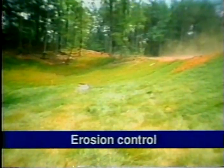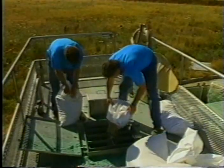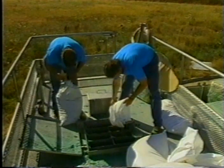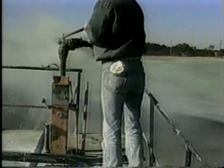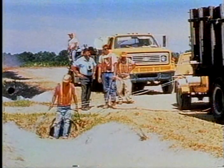Most erosion control methods aim to promote and sustain the growth of grass or plants, which will ultimately hold the soil in place. Hydraulic mulches of natural materials like cotton waste, gypsum, or wood fibers mixed with acrylic tackifiers and indigenous seeds are an inexpensive and rapid way of seeding accessible areas. These creels hold polypropylene fiber roving, which will be forced through a gun by compressed air to form a cover of interlocking fibrils to protect seeds from rain and runoff.